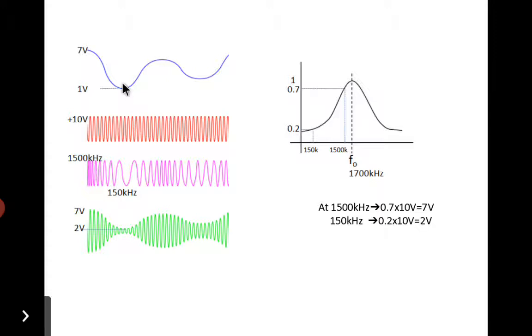Now as the amplitude of the message signal decreases, here the message signal amplitude decreases to 1 volt. Now the frequency of the output signal decreases. So let this frequency be equal to 150 kilohertz. Now we are going to give this FM signal to a slope detector circuit to recover the message signal. In the slope detector, this FM signal is now going to a frequency selective circuit and an envelope detector where we get the original message signal.